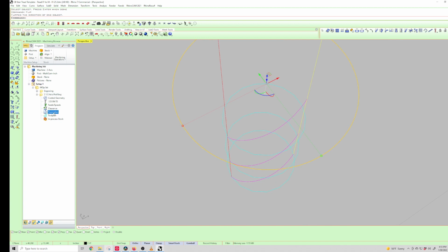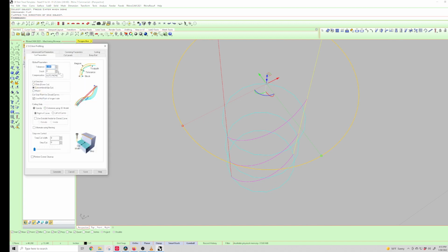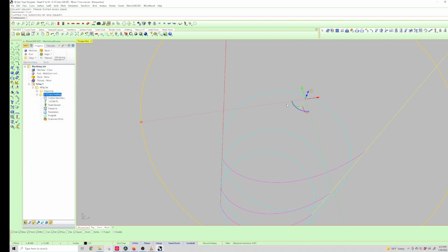So we go back to parameters. See this tolerance right here? That's that light blue line. You can see how it's line segments like that. This is a pretty small curve, but you can see these straight lines. So I'm just going to add a 0 to that, so now you have 0.0001. Now watch these lines here when I do that. It turned it into a curve that, unless you zoom way in, you can't tell. If you zoom way in, you can start seeing that those are straight lines also, but that's that tolerance level. All right, we'll just leave it at that.